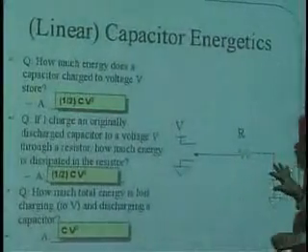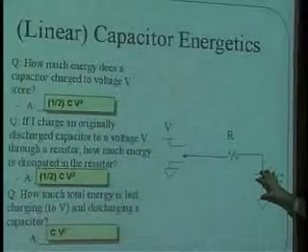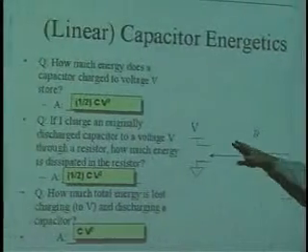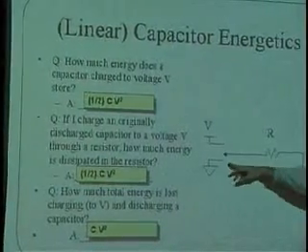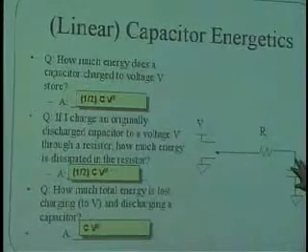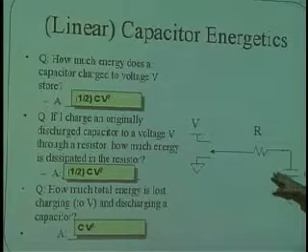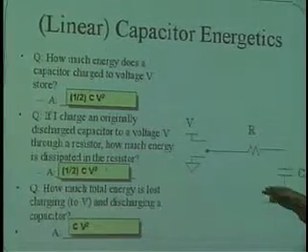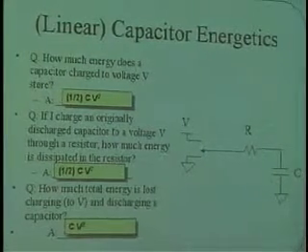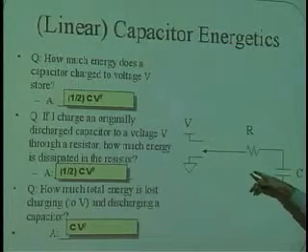Okay, let's take a look at the diagram on the view graph here. We have a certain amount of energy, 1/2 CV squared, let's say, stored in the capacitor, because this guy's all charged up. And then we throw the switch to the other side, hooking this to ground. So the 1/2 CV squared is in here, and we know the resistor will discharge it all the way down to ground. Where's the energy go? It can only go into the resistor.